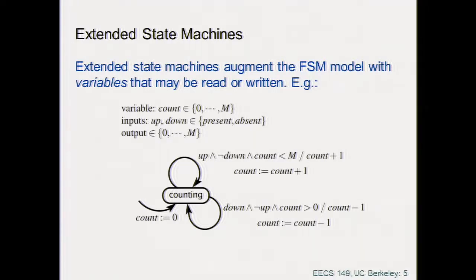But it simplifies the notation of a finite state machine greatly. So what you do is that you encode that information that the state is changing, right? Always the same, goes up and goes down, etc., is captured by the self loop and by the variable that is assigned with a transition. And so that variable grows by one or decreases by one, and that takes into account all what we said. Now, notice that the condition under which you take a transition, a self loop, contains the variable that you have inserted, the count variable. And so if count is larger than 1, then you can decrease. If count is equal to 0, then nothing, it doesn't make sense to decrease because it's an infeasible situation. A car cannot leave a place where there is no car, right? So that is what this representation does.